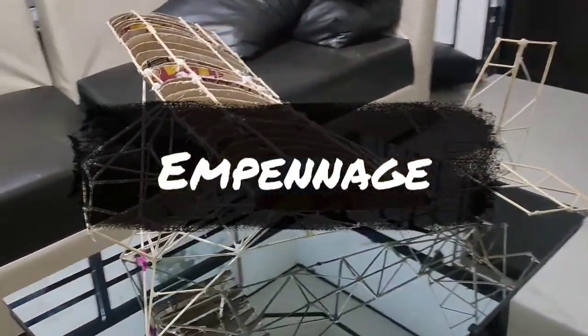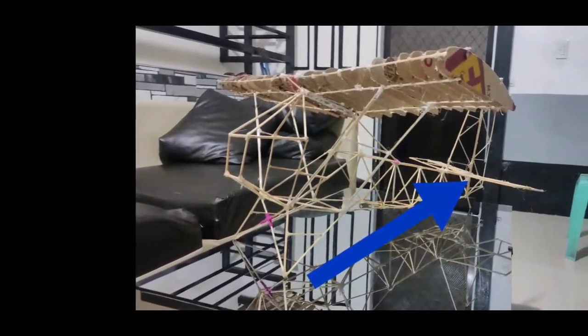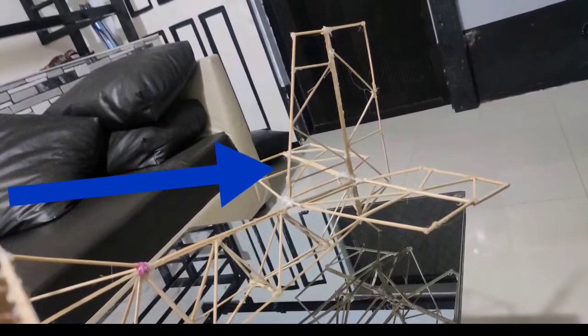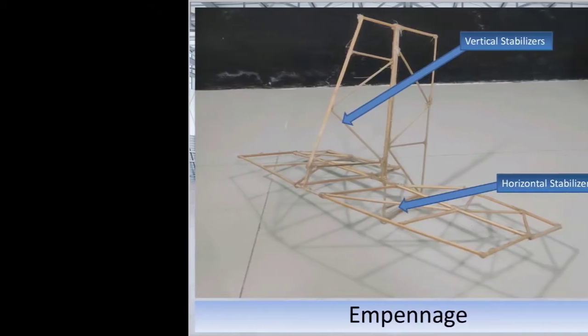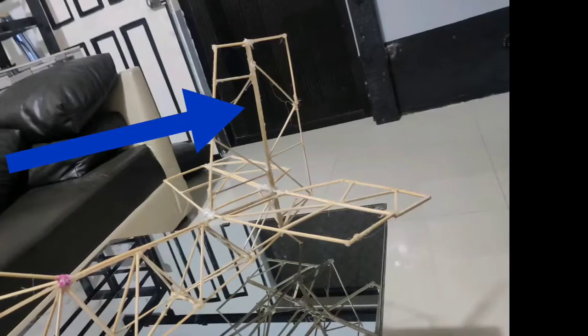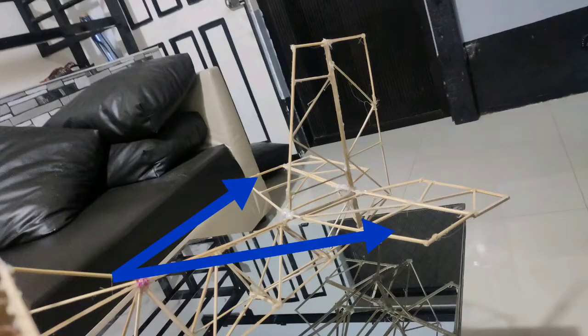Let us now proceed to the empennage. The empennage is the whole tail unit at the extreme rear of the fuselage, and it provides stability and directional control of the aircraft. In the empennage, the horizontal stabilizer keeps the airplane's nose from moving up and down, also called the pitch. The vertical stabilizer allows the airplane to weather vane into the relative wind. This helps prevent the side-to-side motion of the aircraft's nose, which is called the yaw.